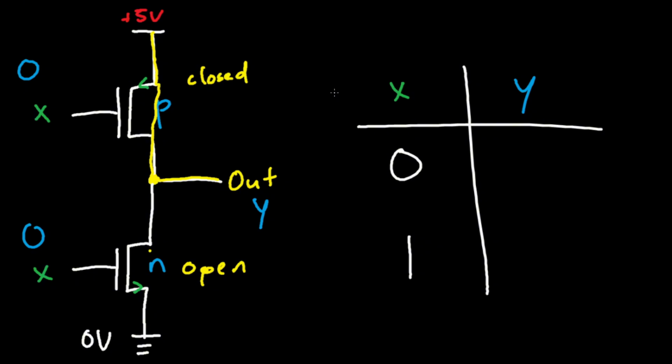And it goes out. Well, since you actually have 3 to 5 volts at this node, what does this stand for? It stands for a logic of 1. So when you have 0 as your input, your output is 1. And keep in mind, the reason why this transistor down here is important is because, boom, this guy acts as an open switch when you have a logic of 0. And therefore, this current cannot reach ground. So that's important. Your current must not reach ground.